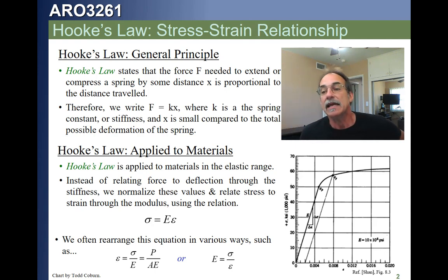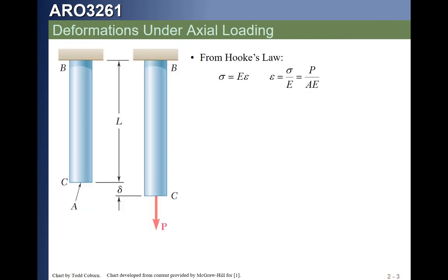Okay, so since we can write the modulus, we can write our stress-strain relationship using Hooke's law here. We can rearrange this and say the strain is just the stress over the modulus, which is the stress over E. This is going to set the groundwork for calculating our deflections on the next slide.